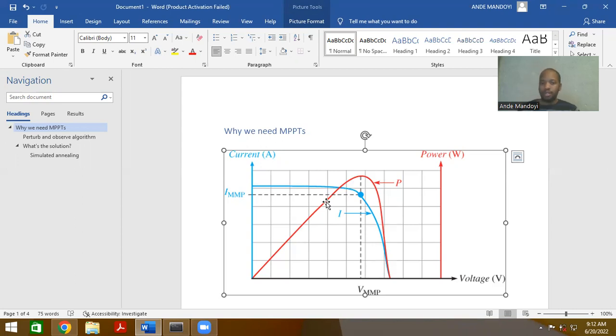That's not right. What if you then increase the voltage indefinitely and you increase it to this point? Still, you're not getting full maximization of that solar panel. And somewhere in between these two extreme points lies what we call the MPP, not the MMP. I don't know what I was thinking there, which is the maximum power point, the voltage at which you're going to get maximum power for that specific load.